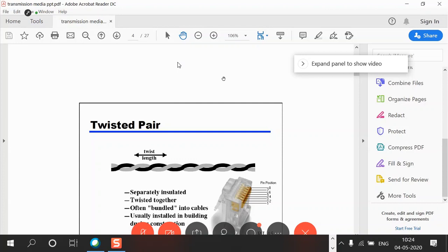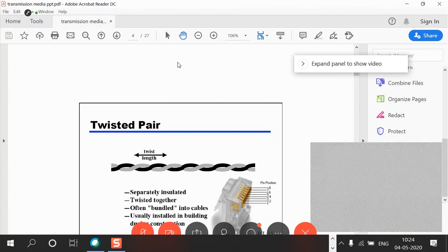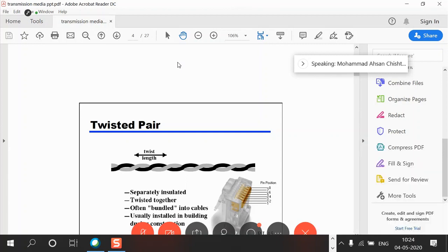Inside it, there is an insulated copper wire, which is a very small copper wire, typically of the dimension of 1 millimeter in both of these. Now, these two wires are twisted together in a helical manner. You might have heard of this, like the DNA helix. That is the twist that you have here. Now, why are these twists made here? Twists are made to reduce the electrical interference from what? From a close by pair.